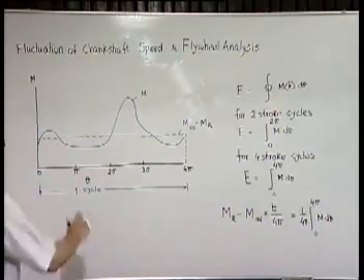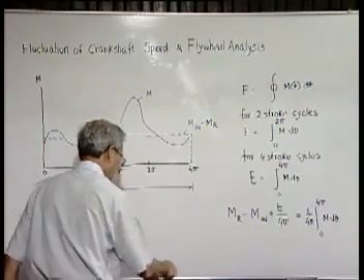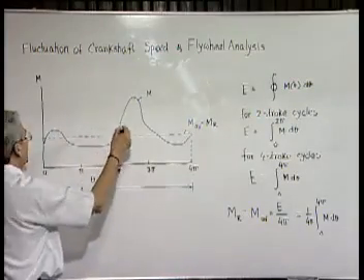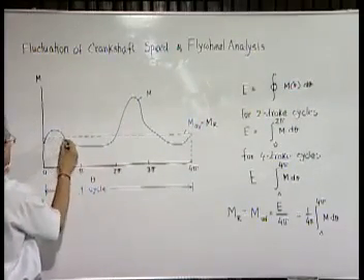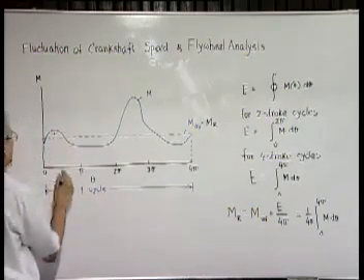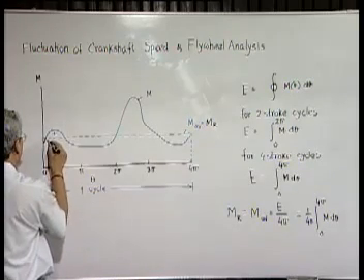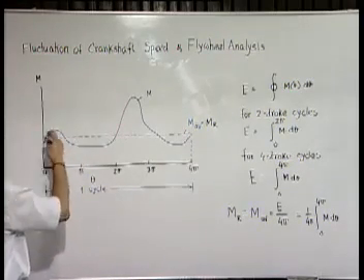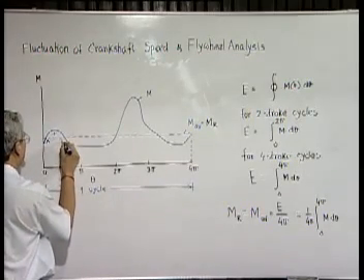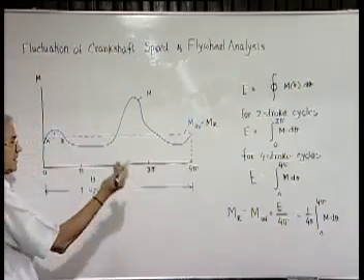Now we find that if we draw this resisting moment, in some places the driving torque is above this resistance, and in some cases the driving torque is less. So here what will happen? Energy will be added to the system, so the kinetic energy will go up till point B, after which the driving moment becomes less than the resisting moment.